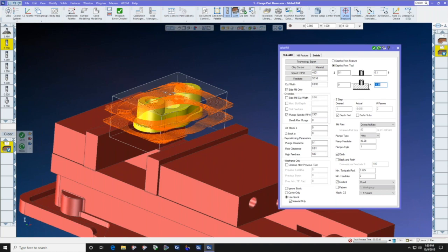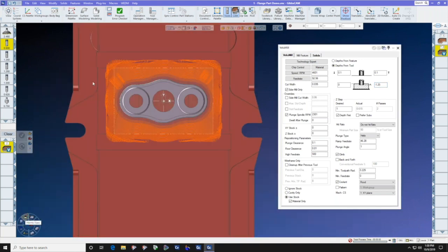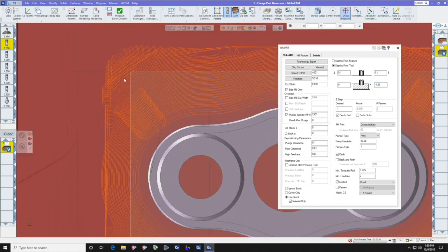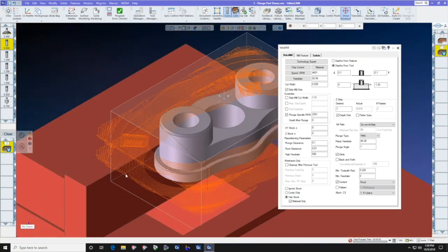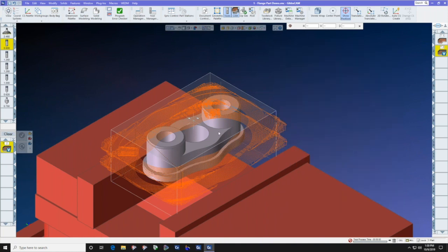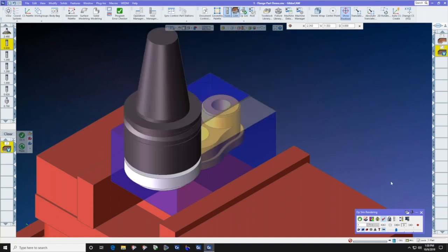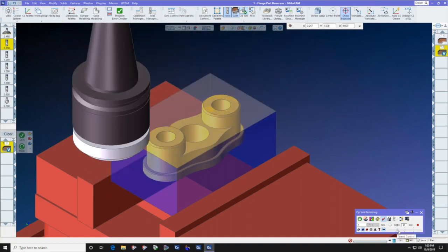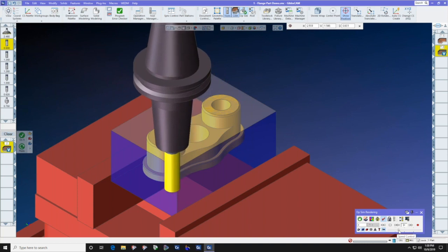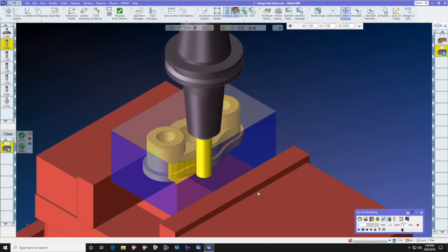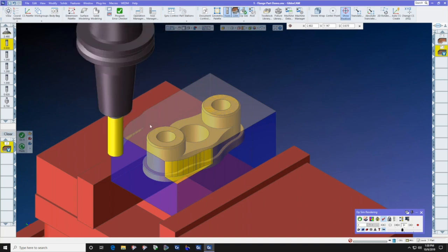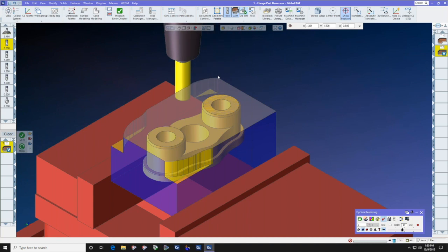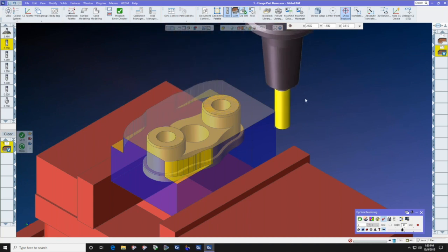If this is the first VoluMill toolpath that you've seen, you'll notice from the top that it looks like a bowl of spaghetti, because VoluMill was designed by a scientist and a mathematician. I'm going to show you that VoluMill toolpath right now, let you watch it run. Again, it's twice as fast and 4 times better tool life because we get to use more of the tool's depth, because in this case, we're only using about 10% of the diameter of the end mill.